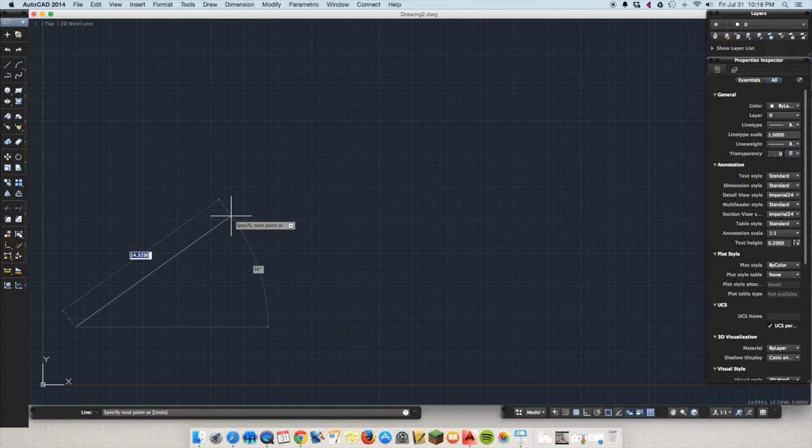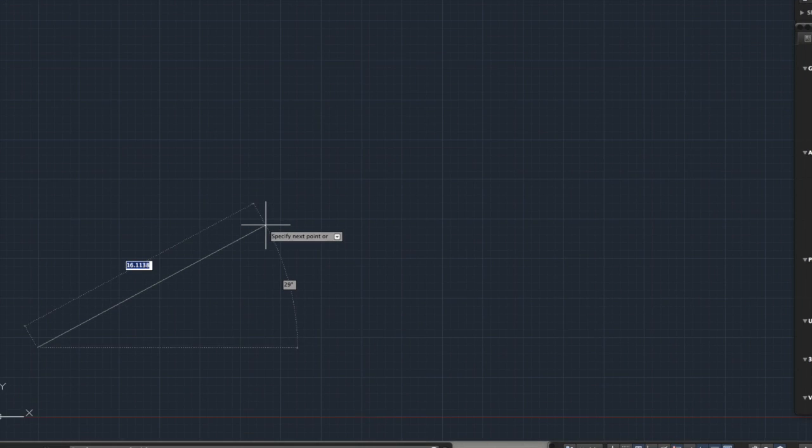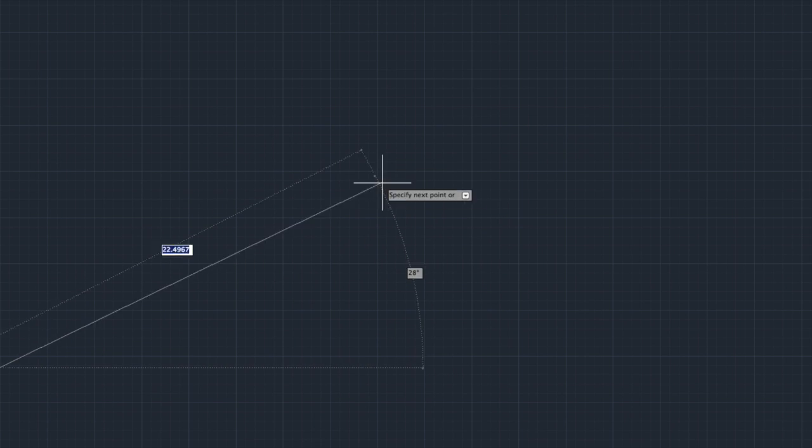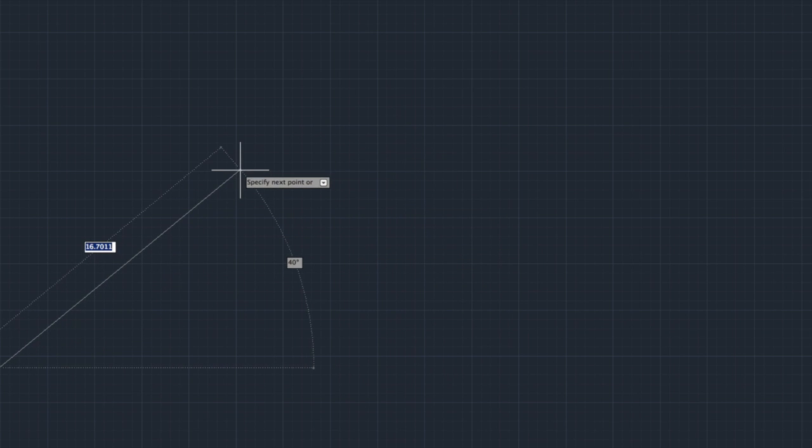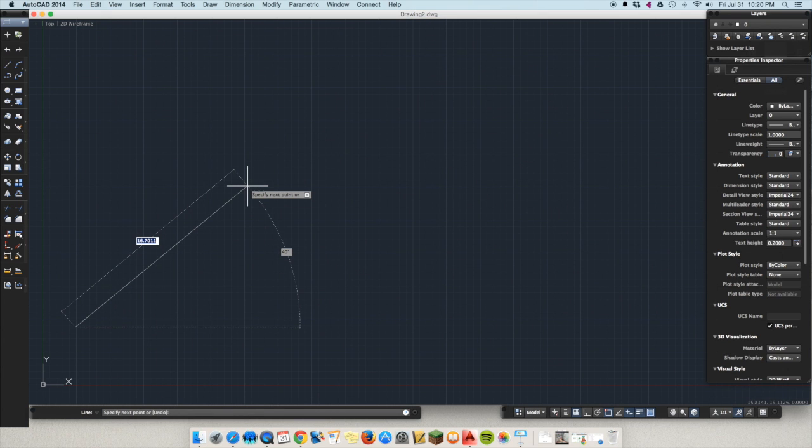Now you can actually see that I can get the distances and the angles. I'll show it to you up close. Distance and the angle as I move, but I can also just type them in, which is probably going to be much, much easier for you, because lining them up at exact units is a little bit tricky. So here's what we're going to do. To start with the first one, let's do a distance of 10. I'm going to type in 10, and then I'm going to do angle sign, and that's going to jump me over to the angle part, and I'll do 90 because it's an easy one.